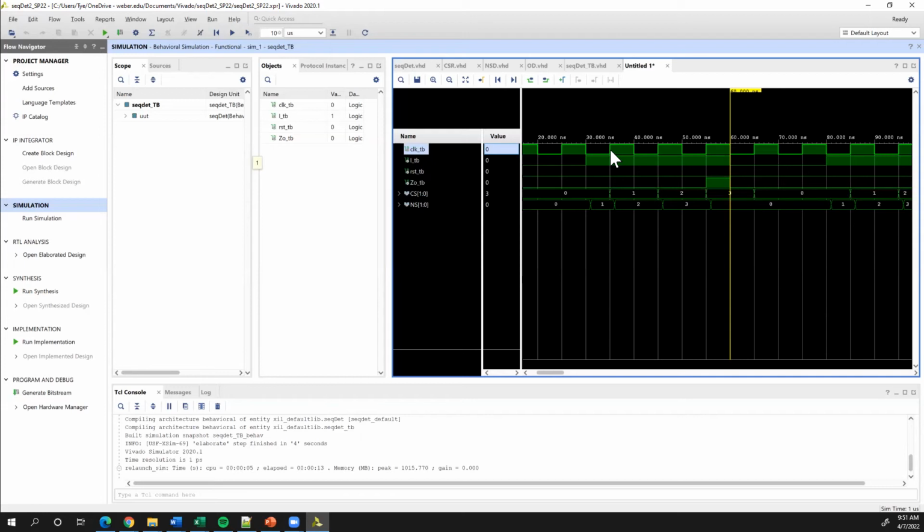So in the case of a Moore state machine, if I want to detect three numbers, I need 4 states. Moore state machines tend to take more states, just because I have a state dedicated strictly to letting me know what the output is, right? And so I simply say we need 1, 1, 0, and this state is where Z is detected. It's true inside of that last state.